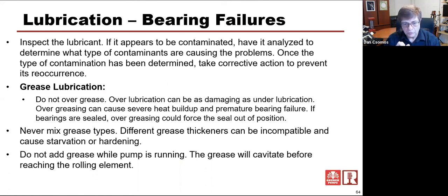You may have an oil spray, where they're actually spraying oil onto a bearing, or an oil drip. The best type of lubrication of any kind of bearing is actually an oil spray, where that spray is coming onto that bearing on a consistent basis. It's getting a nice lubrication as it's running, and that's the most reliable. However, that's the most expensive and most difficult way to lubricate a bearing.